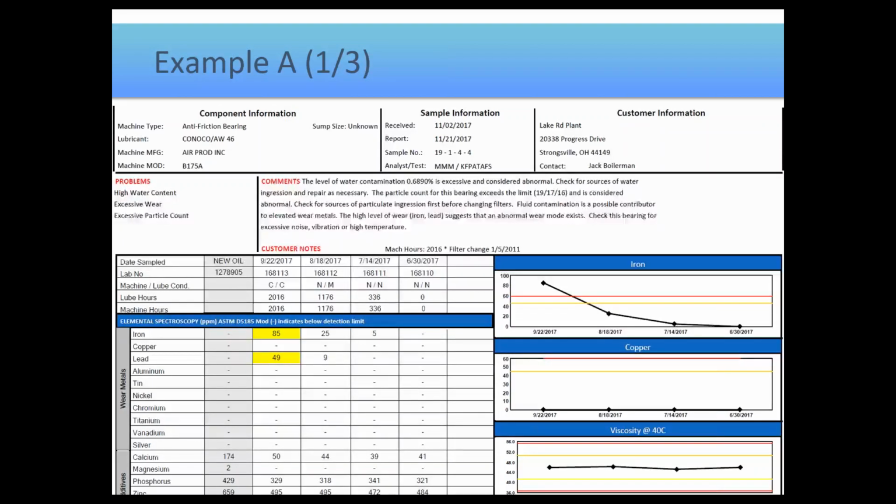So hypothetically speaking, let's pretend that we do tell somebody to inspect for sources of ingression. Look for ways particulate and water could have gotten in. Imagine I tell you that the problem was so obvious it could be spotted from 20 feet away from the machine. The dipstick was laying on the ground, or the fill cap was missing, or the breather was damaged or missing. Something really obvious. So of course, the corrective action would be to fix or replace that.